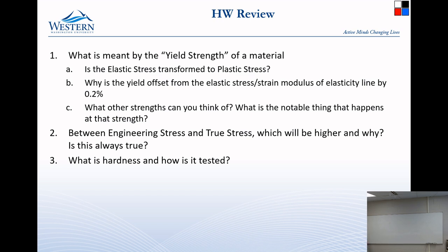Right. Okay, so I unfortunately don't have anything here that's metal, but I'll use this fine twist tie that I found. If I bend it, it's elastic, elastic, elastic. Okay, it's starting to be plastic right there. If I let go, it springs back. So the elastic stress does not get converted to plastic. There is still a loading of elastic stress that is in that part, and when you unload it, it will spring back. And actually, you know this intuitively.